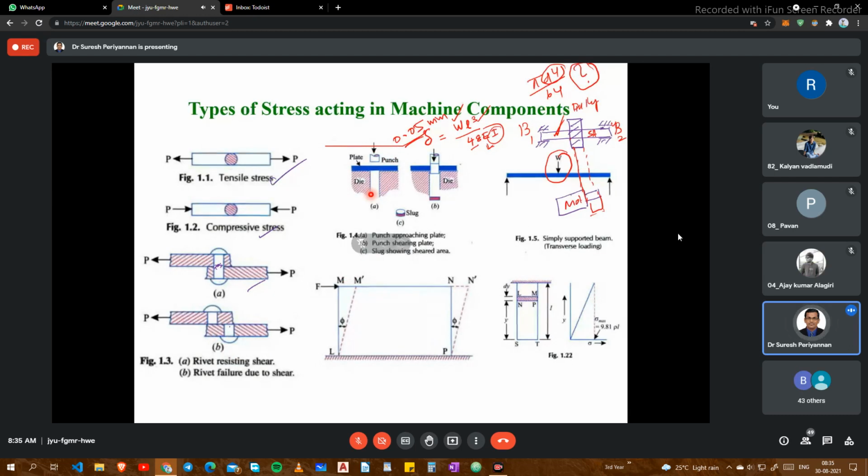We connect two components with the help of a bolt and nut, using washers. The washers are made from thin sheet using the punching operation. While preparing the washer, it is cut with the help of the punch due to the shearing force, the shearing effect at the side of the washer. With this shearing effect, the washer is cut from the thin sheet.